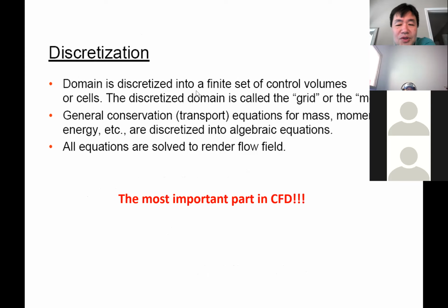Some words I want you to learn. The most important word in the CFD world is something called discretization. If you type this word in Microsoft Word, it doesn't recognize it and puts a red line below it. Basically, that's a new word created by the CFD industry. It means you transform the original differential equation into an algebraic linear equation set, which is called a matrix. The computer is solving the matrix.